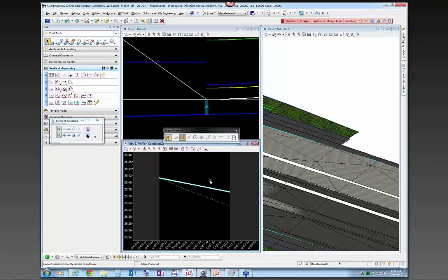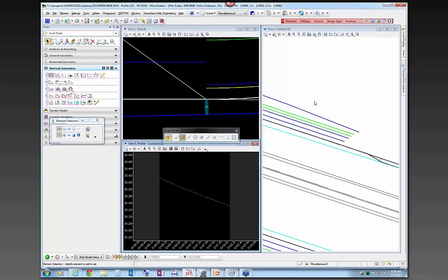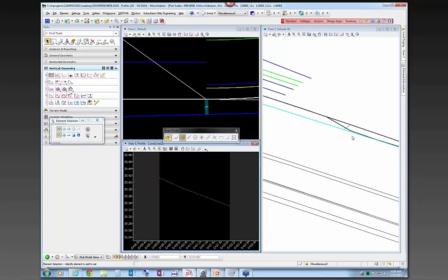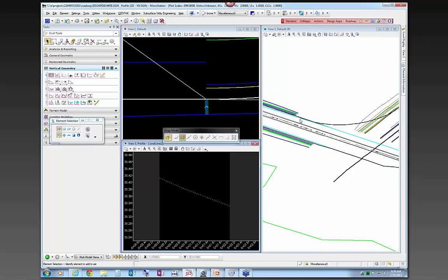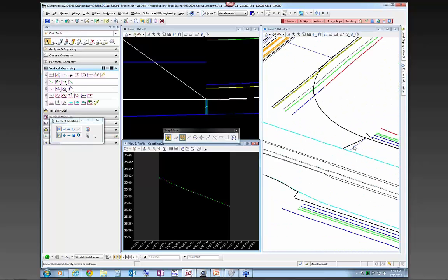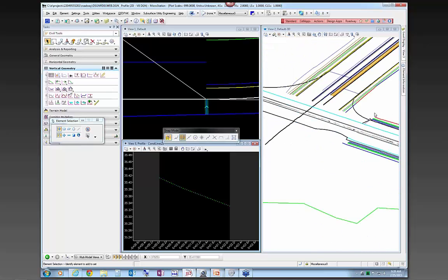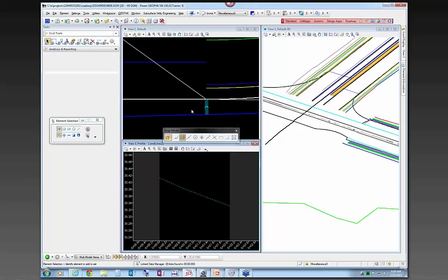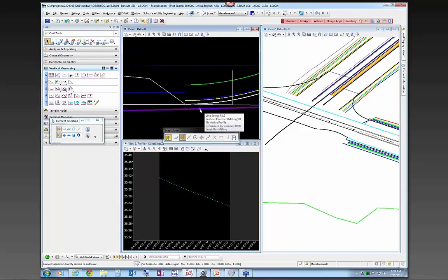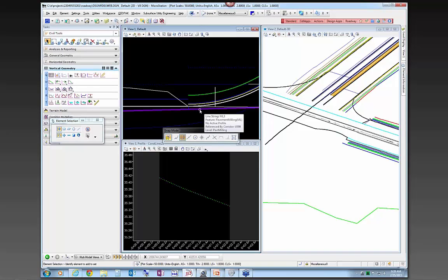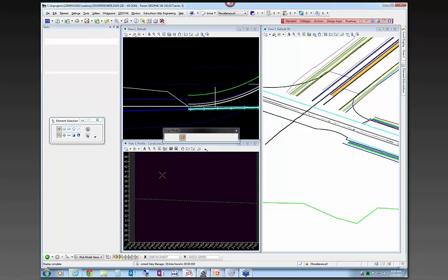And now once that's set active, then if I go ahead and turn off these corridor components again, there's the new line there, and there's a new line over here. And then I'm going to come back and get these traffic separators in a second, but what I'm also going to do is find this line here and go to its profile, select this view.